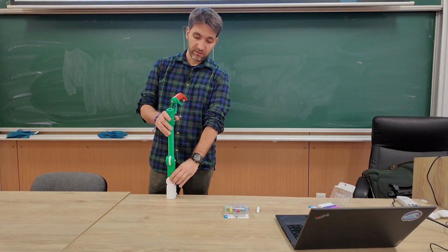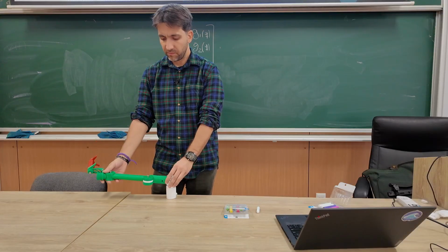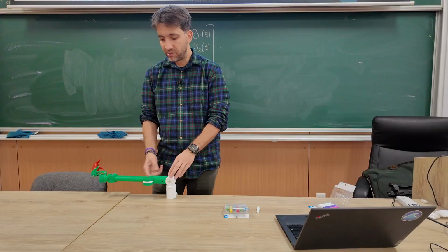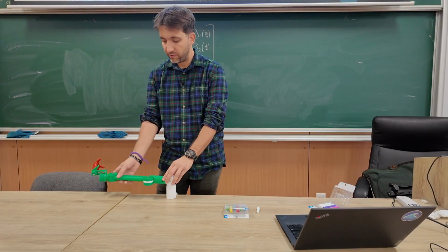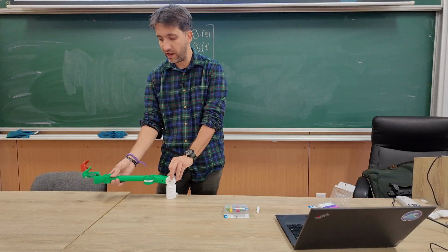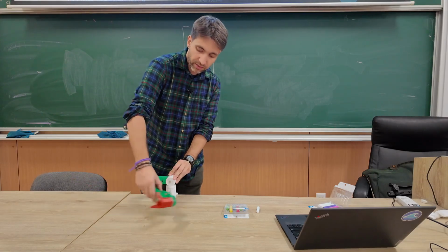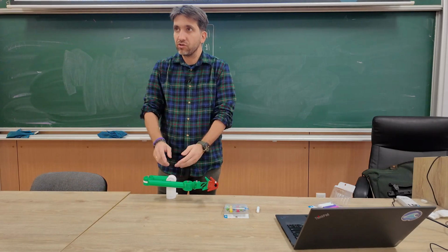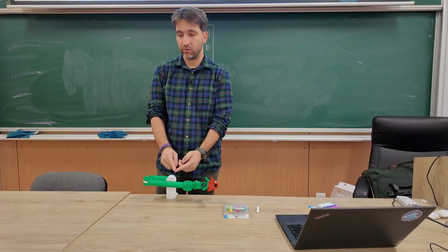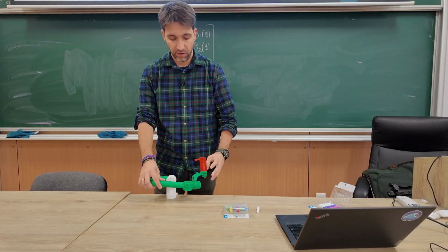So that's one simple example of how, let's say, in this example it's just this joint affecting its own joint, but I can have the other joints affecting this joint as well, right? So here again I have the masses further away from the axis of rotation, but I might do something like this, and now the masses are closer, or even on the other side, so I might have different torques due to gravity being generated also due to the other joints.